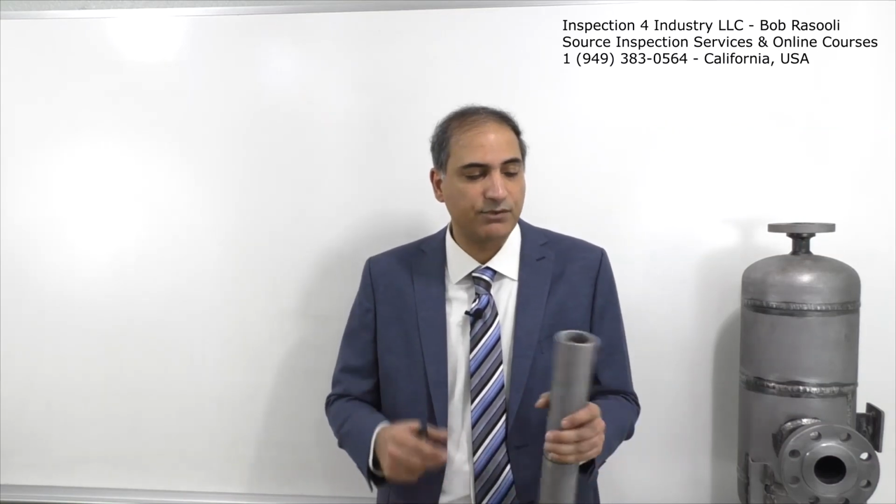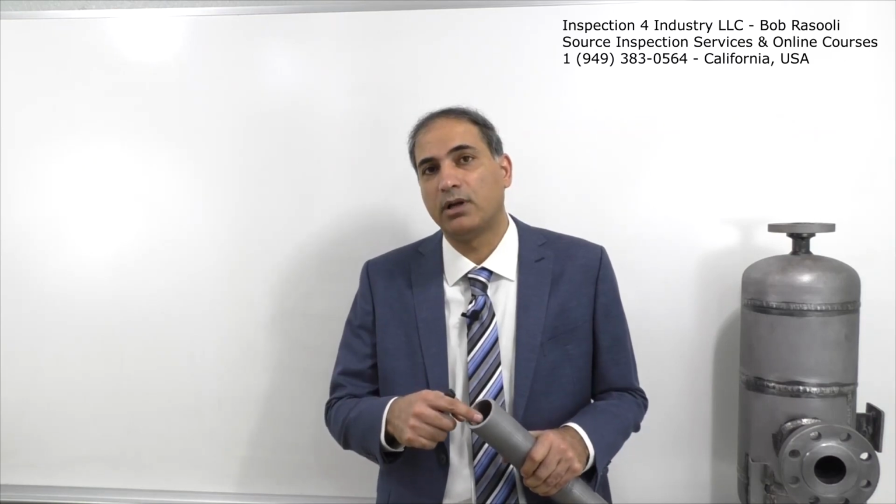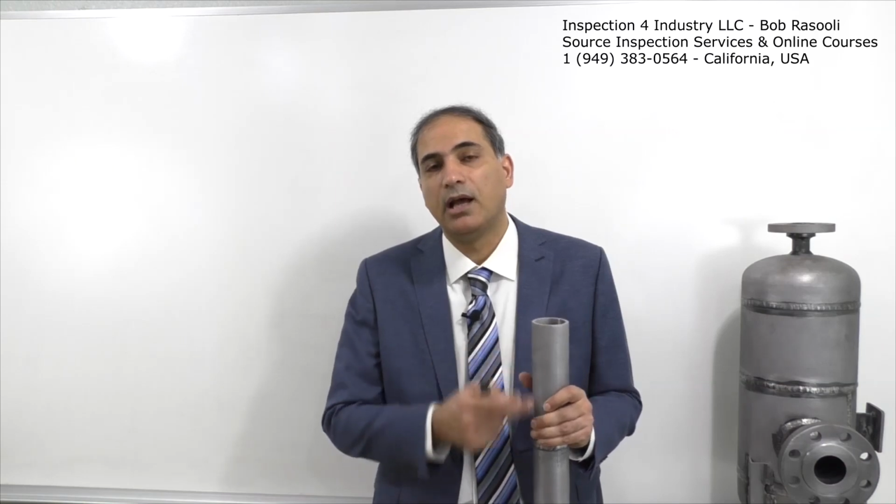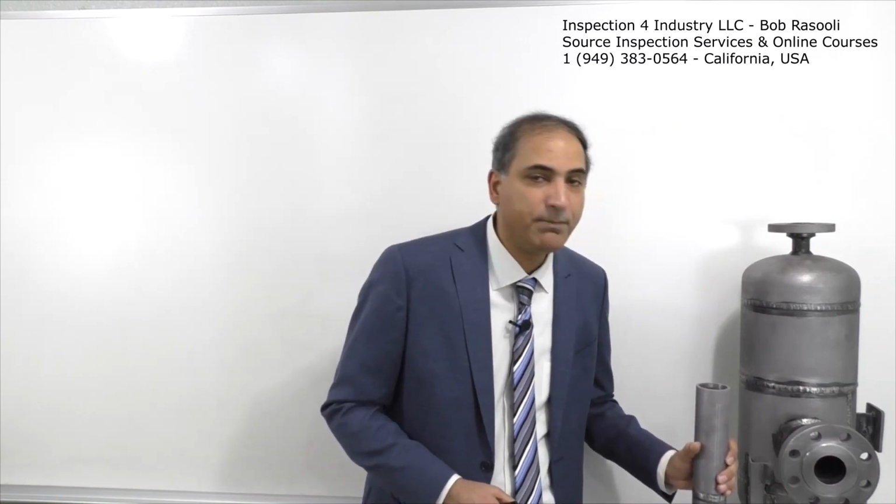you should be able to calculate the wall thickness for internal pressure, which we name hoop stress or circumferential stress. The hoop stress acts on all 180 degrees of the pipe and wants to tear the pipe apart from here. To overcome that hoop stress, or circumferential stress, you need some wall thickness to resist it.